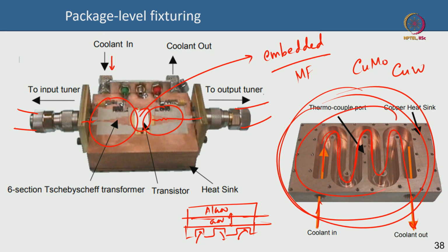See, here the liquid is kind of far away, you have the package, you have the flange, and you have the metallic fixture below. So, it is quite far away. Although it takes the heat away, the heat extraction will be much more efficient when your liquid is flowing very close to the active channel, but you cannot bring it too close because it will affect the impedances of the RF. So, there are many things there. This is an active area of research, just to mention here.